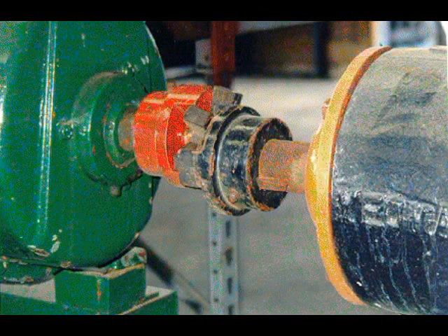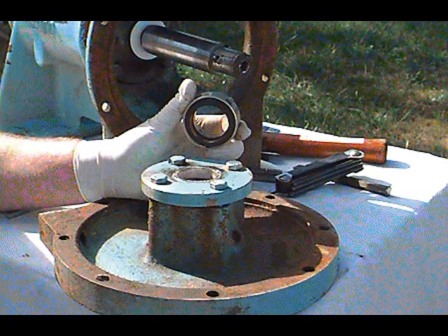A mechanical seal might fail because of misalignment. Misalignment can be caused by excessive vibration of the motor and pump, or improper installation of either of the units, or the mechanical seal itself. If the seal is installed so that mating faces are not parallel to each other and perpendicular to the shaft, the rotating face will try to square itself with the seat, causing uneven wear on the mating surface. To prevent this problem, the seal must be properly installed. The rotary unit must run parallel with the shaft, and the stationary seat must be perpendicular to the shaft.